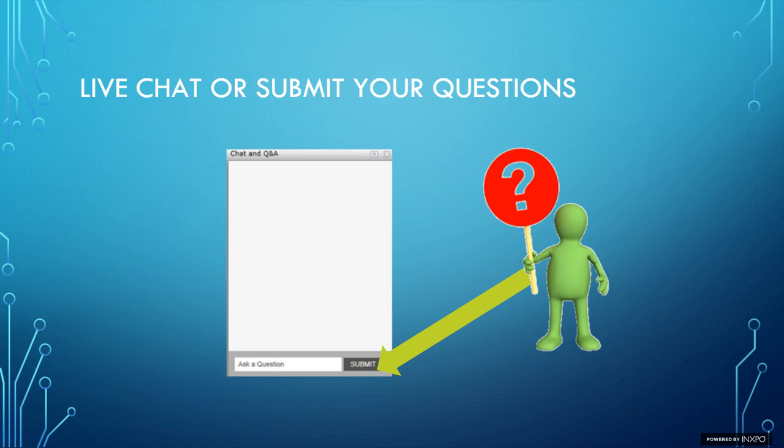The compressor itself is less efficient to operate. It means your energy cost to get the same amount of air at pressure will be 7 to 20% higher. Some people might say that the cleaner treatment that's required for the lubricated one would be offsetting that. That's not quite true because, as we stated, any compressor type would require a certain type of cleaner treatment. So for me, this is almost a wash.